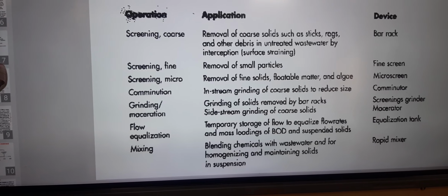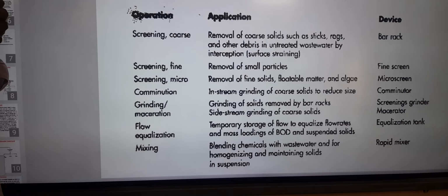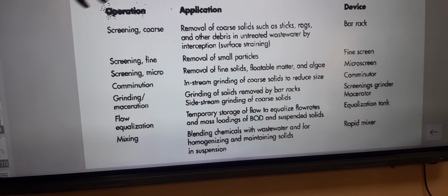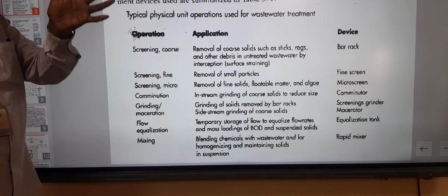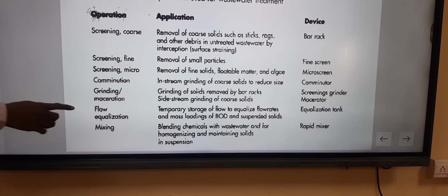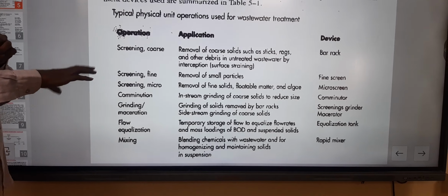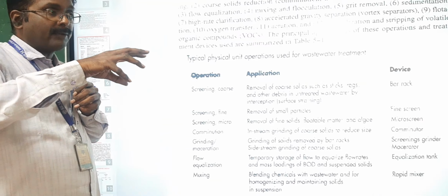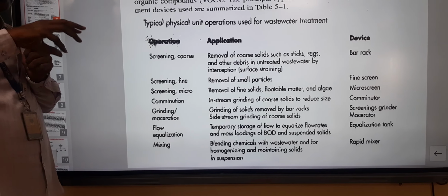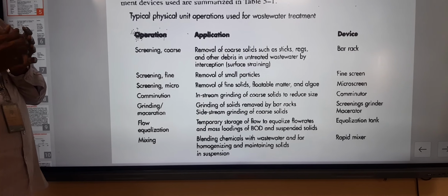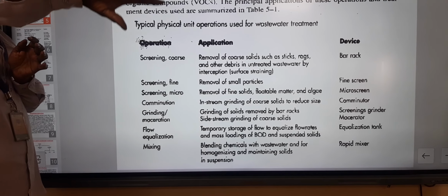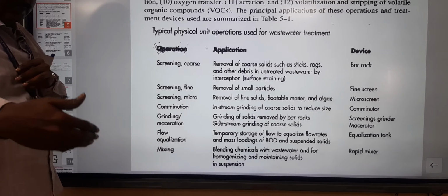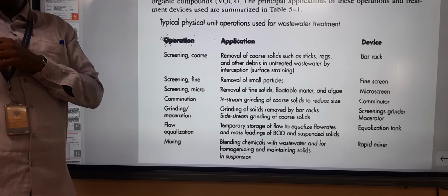So for that, the company has a small water pond where they collect all the waste coming from the industry. All the wastewater is stored in the pond. That pond is what we call a flow equalization tank. It is like a buffer tank, which adjusts the difference in concentration or volumetric flow rate of the wastewater. Once the wastewater enters the flow equalization tank, it settles for 1 or 2 days. Then from the flow equalization tank, the wastewater is taken to the actual treatment plant.